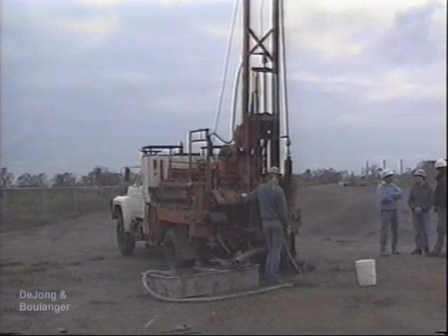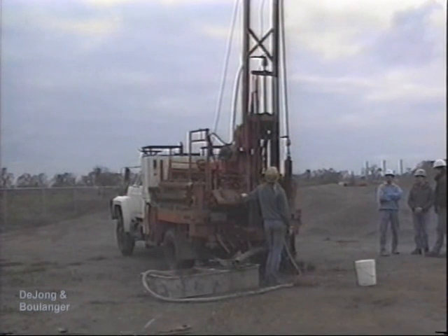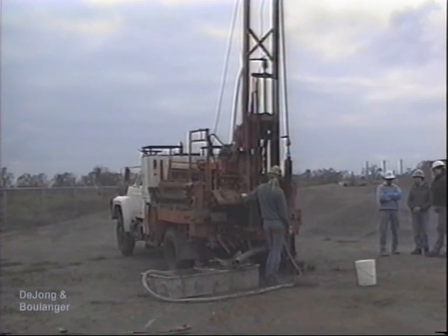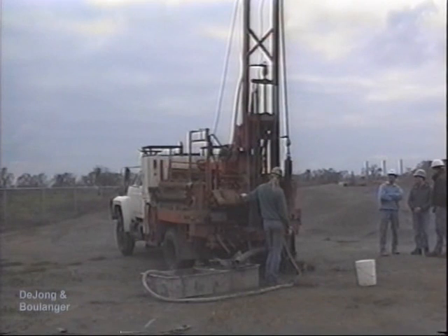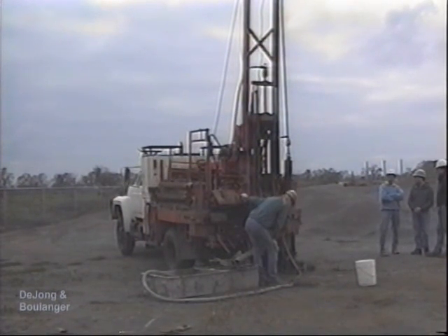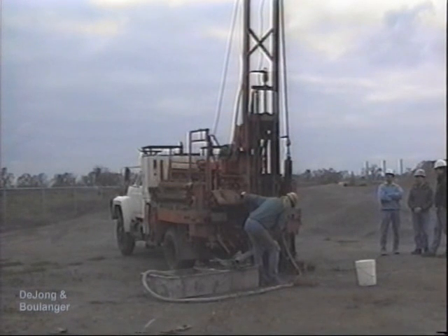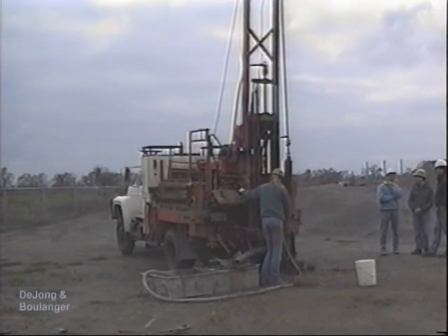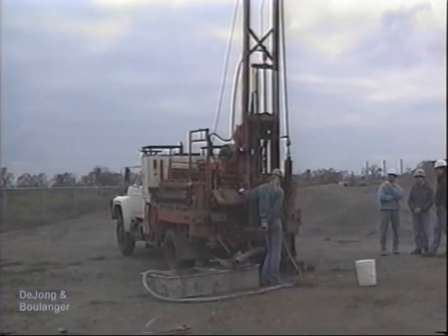The type of coring equipment and operating procedures can greatly affect the quality of the retrieved rock cores. Rock cores can be heavily fractured and damaged by the coring process. Failure to distinguish between natural and drilling-induced fractures on the drilling logs can lead to a completely erroneous interpretation of a rock mass's characteristics. Alteration to the drilling equipment and procedures can significantly improve the core quality and percent recovery in many situations, and these changes should be recorded on the drilling logs.